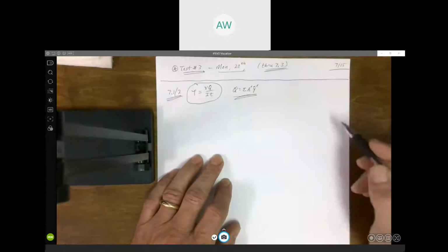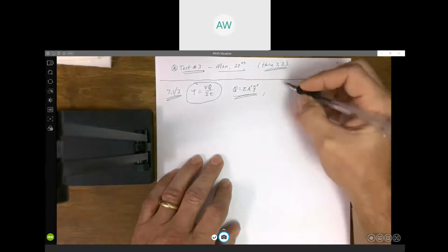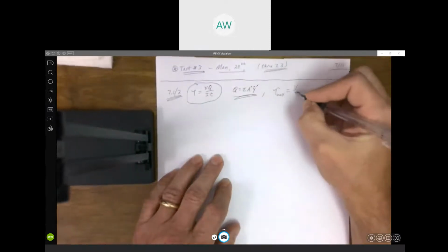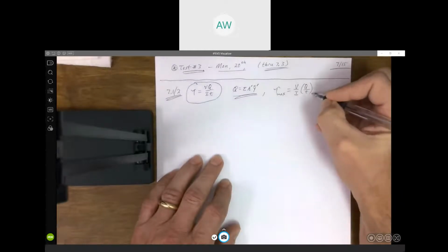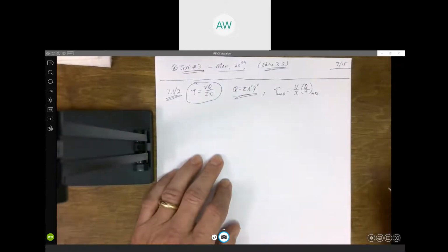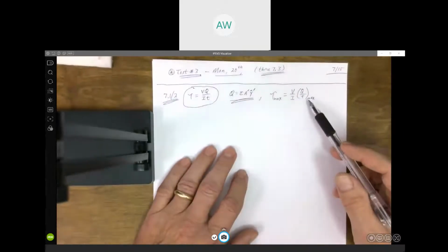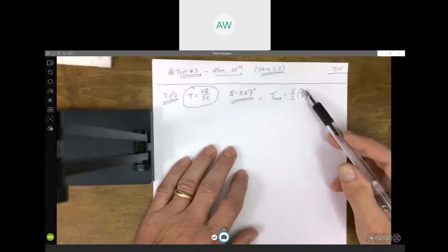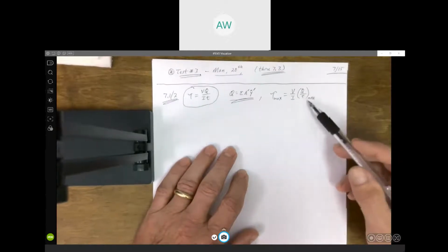And one of the last things we talked about was if you want to find the maximum shear stress acting on that cross section, it's going to occur where this ratio, Q over T, is a maximum. And again, Q is always going to be a maximum at the neutral axis. So that would give you the largest numerator. So if your thickness, the denominator, is the smallest at the neutral axis, then that's where this ratio of Q over T is going to be a maximum.